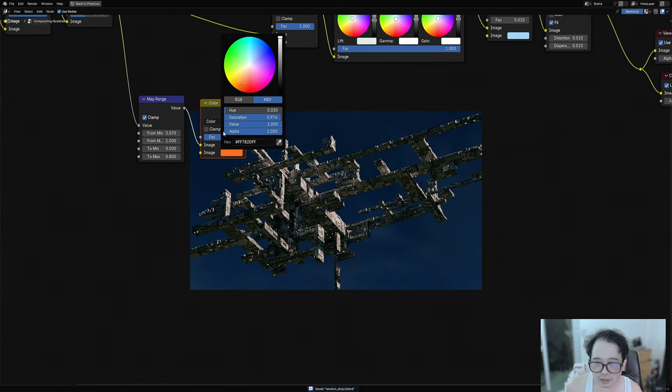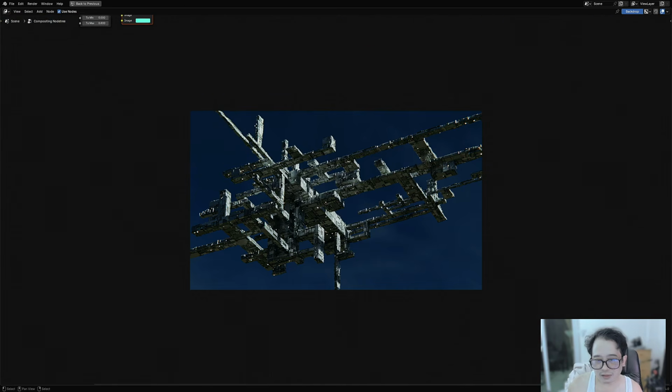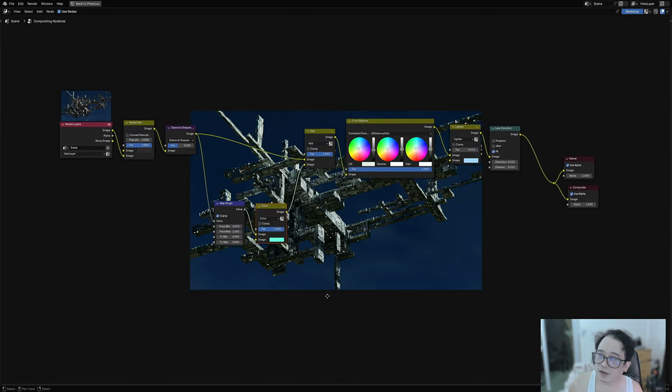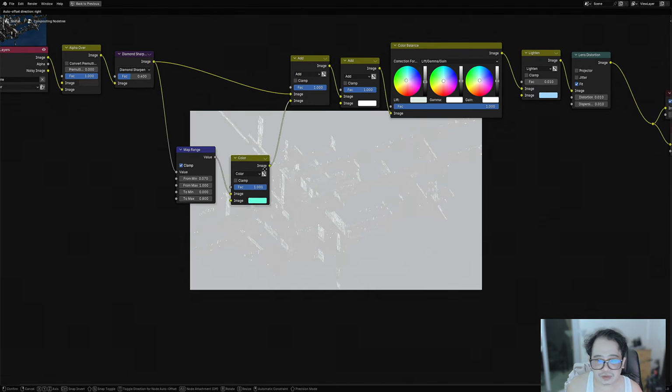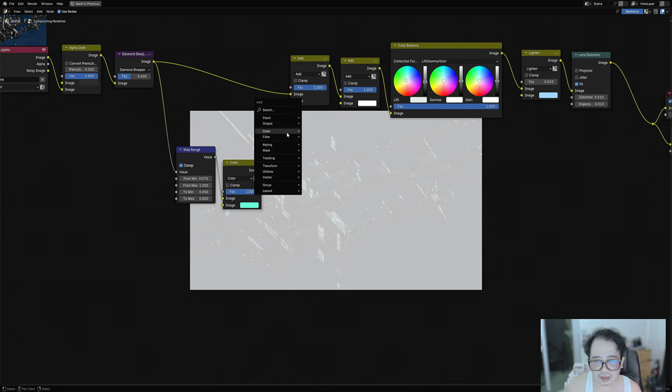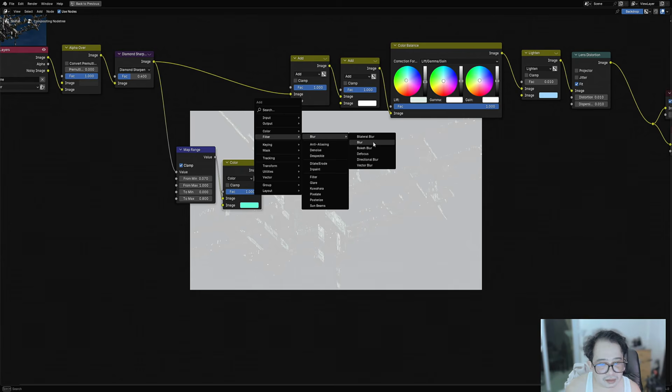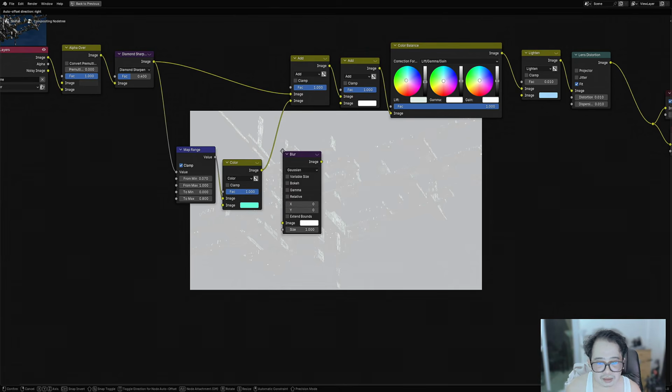Then you can use the color factor in the color mix node to change the color of the highlights. So it's sort of like that. And also other effects like, if you use filter, I mean blur and fast blur, fast Gaussian.